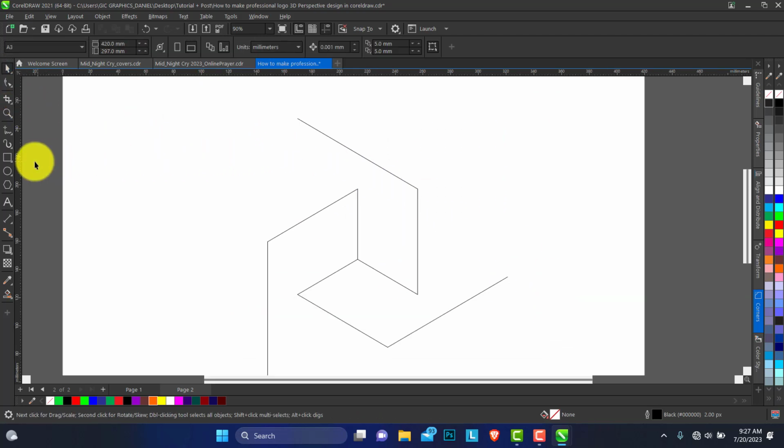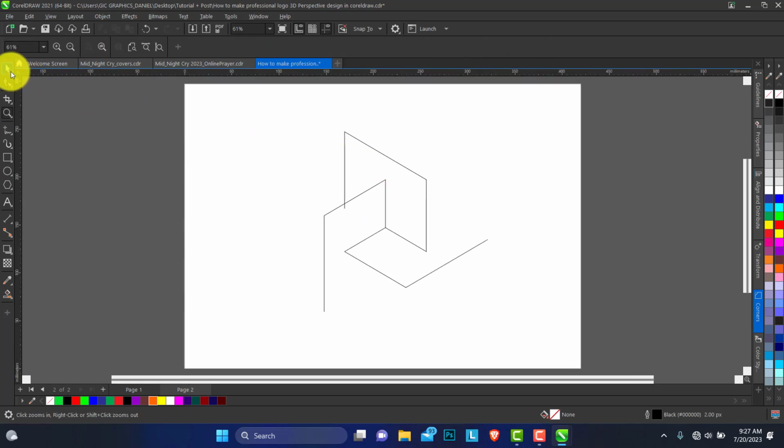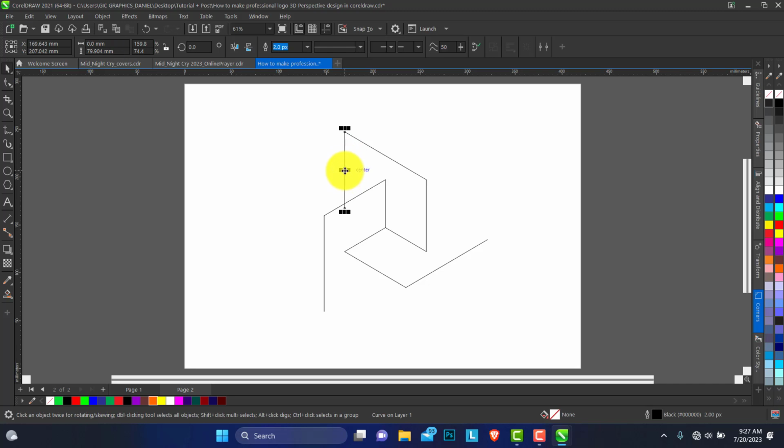Few more steps and we'll be done. You can copy another line. This time, make sure this line intersects with this existing one. We do the same thing: take the center and rotate this to 120 degrees, then Ctrl R to repeat the action.